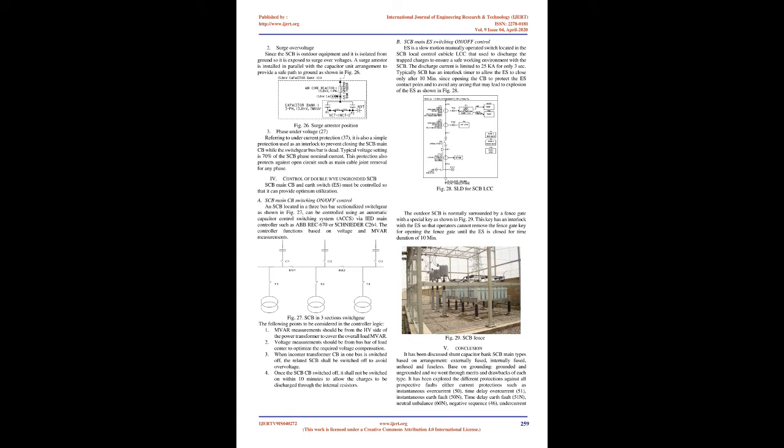Surge overvoltage. Since the SCB is outdoor equipment and it is isolated from ground, it is exposed to surge overvoltages. A surge arrestor is installed in parallel with the capacitor unit arrangement to provide a safe path to ground, as shown in Fig 26.